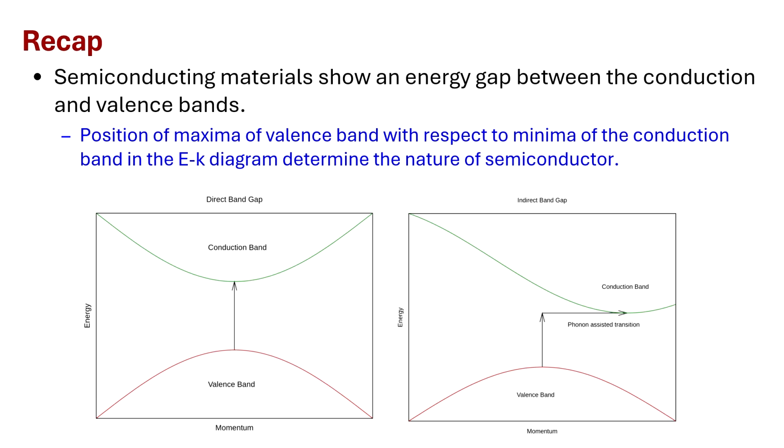Materials like gallium arsenide are direct band gap semiconductors, and they tend to have better light absorption and light emission characteristics as compared to indirect band gap semiconductors, which are shown on the right, where the conduction band minima does not coincide with the valence band maxima. As a result, there is a necessity for phonon assisted transition in the optoelectronic processes, which is an inefficient process as compared to that in direct band gap semiconductors, and silicon is one prime example of this kind of material.